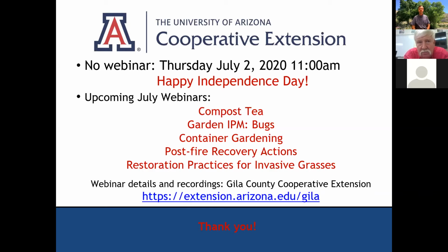What I found in our modules out here at the U of A is that it's the wires, the rubber coating on the wires, and the modules that usually end up cracking because of the high heat, depending on how much strain they were put under when installed. They actually had a set of modules put up by TEP years ago in the early 80s, out here at the Campus Ag Center on poles. A couple are still working. They didn't think they would last that long. And then there's one where the entire module frame fell apart and the components fell through the frame.